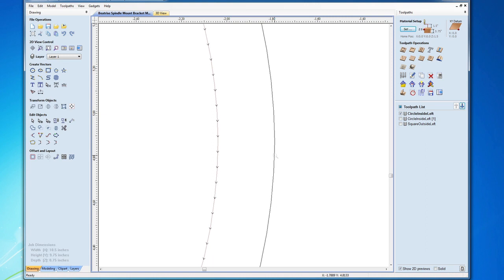And that way, let's say you're doing multiple passes, you can cut that shape out with multiple passes, and then later you can do another toolpath with no allowance and shave off those edges. So if there's any unevenness in the vertical edges that have been machined, those can be shaved off and trimmed off, and you have a nice smooth edge.